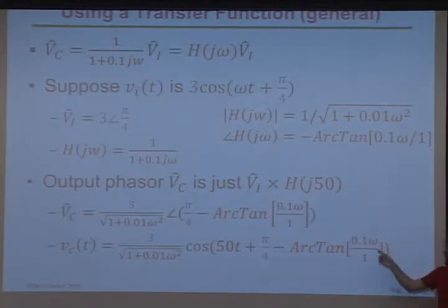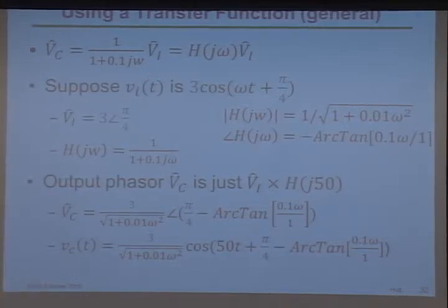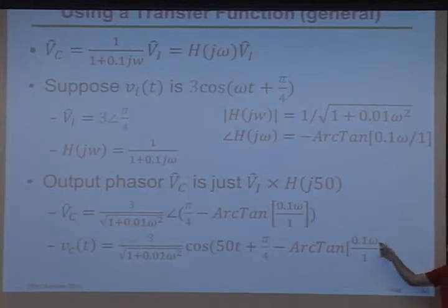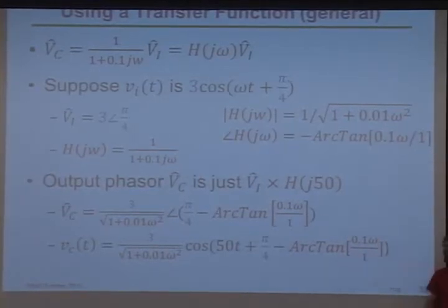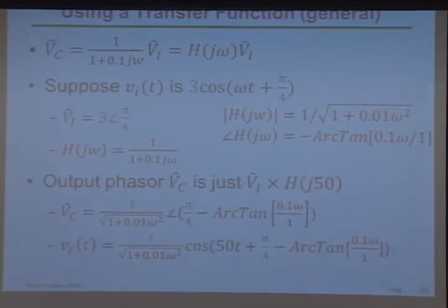So what's the arctan of 0 over 1? Geometrically, if you want to think about what an arctan is, look at this. You've got your real over your imaginary. So what's 0 over 1 going to give you? Yeah. And if omega got really gigantic, what would it give you? Oh, it would go up, but it's a minus, right? I'm going to show a plot again in a second, but basically you can see that as this gets really big, geometrically this number should approach pi over 2, so it'll keep delaying more and more. But I think the next slide should address that.